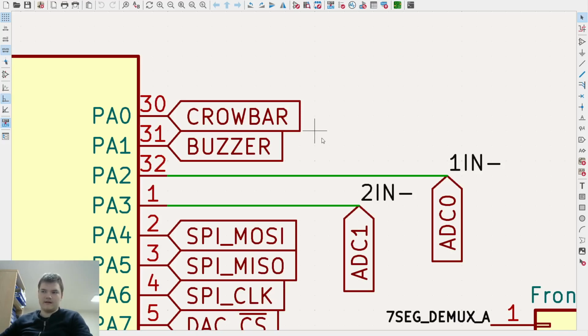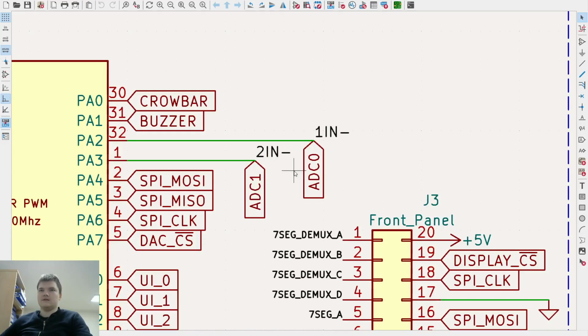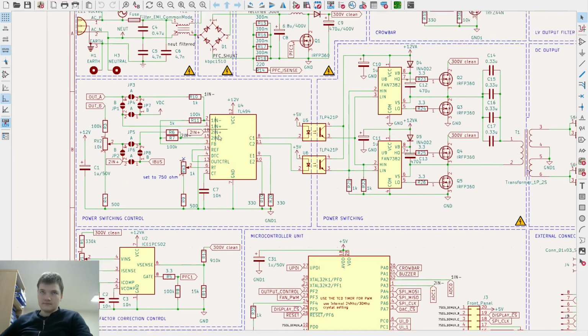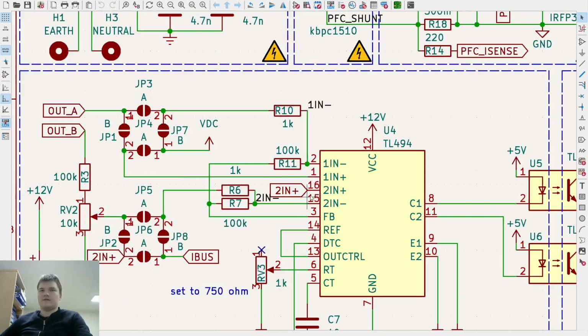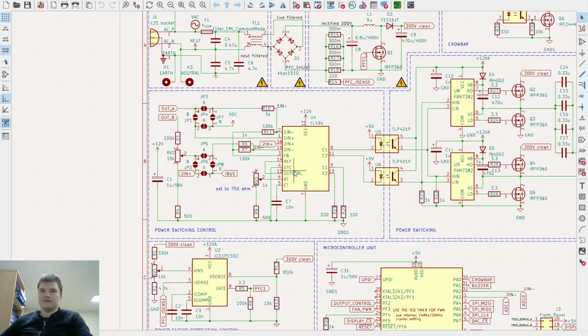That's what the receiving device kind of determines. So basically, if you're in a constant current, you know the current because you set it yourself, but you don't know the voltage because it changes as the resistance changes. And that's basically what these two do. This plugs into the comparator inputs of the TL494, as I mentioned previously, this will need to be verified if this works.